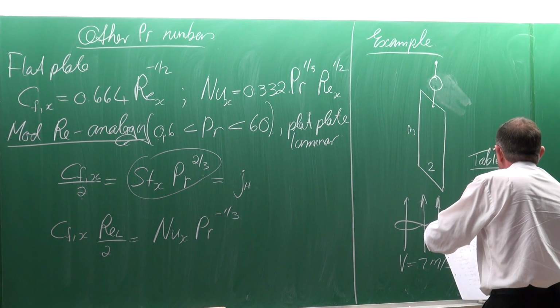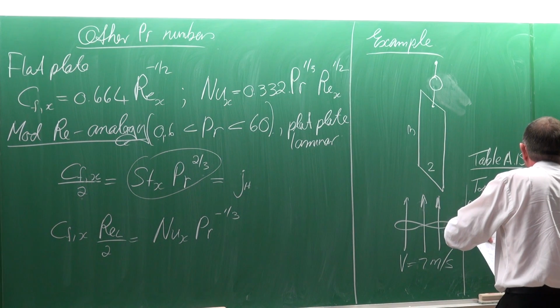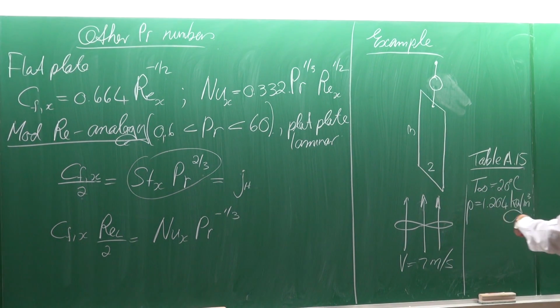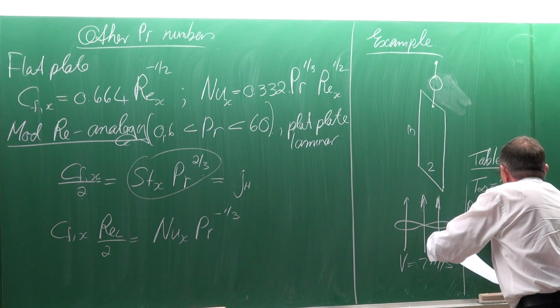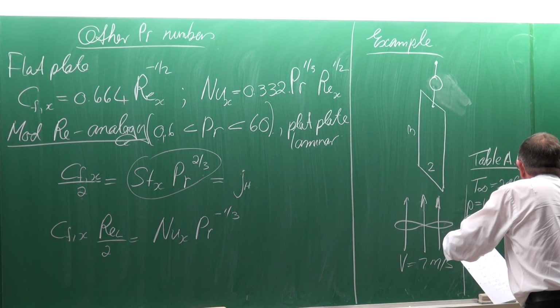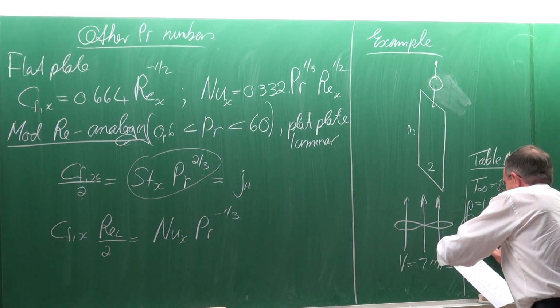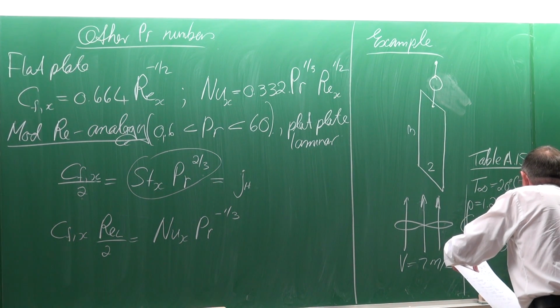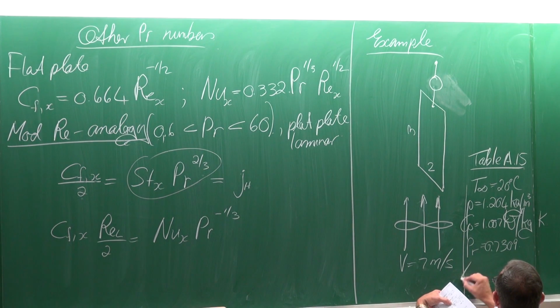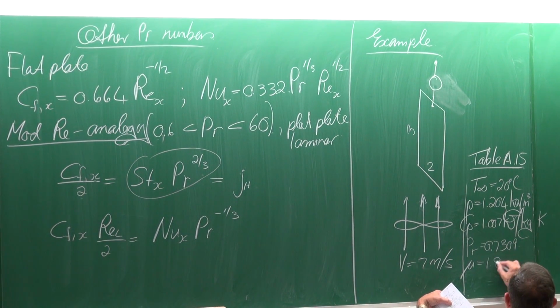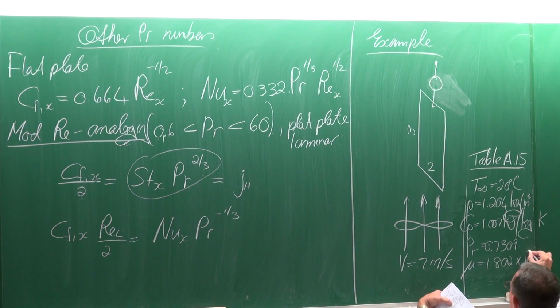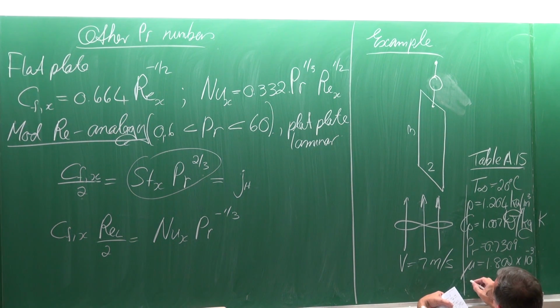The properties for air are a density of 1.204 kilograms per cubic meter, a Cp value of 1.007 kilojoules per kilogram Kelvin, a Prandtl number of 0.7309, a viscosity of 1.802 multiplied by 10 to the minus 5, and a k value of 0.02514.